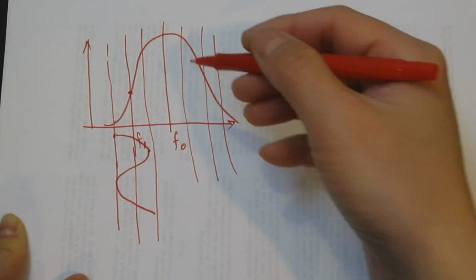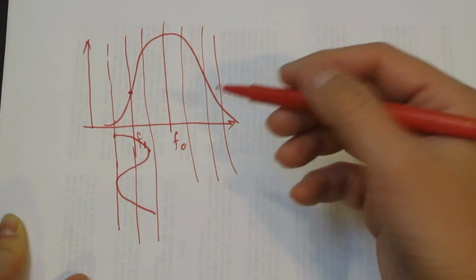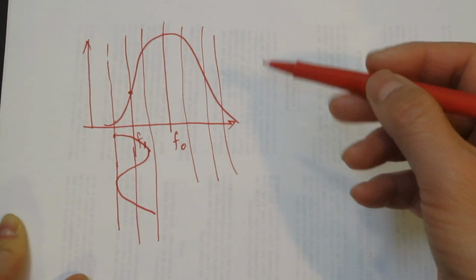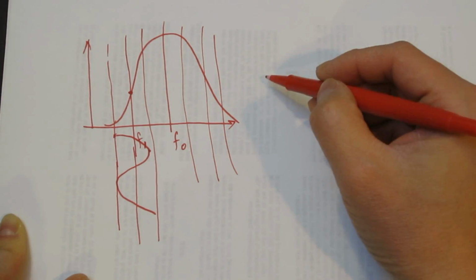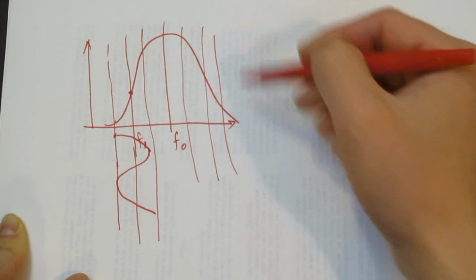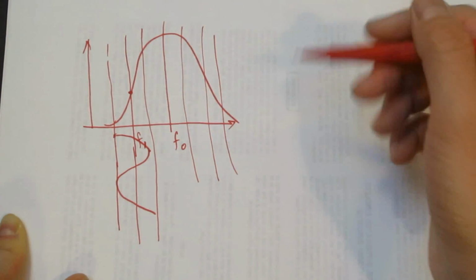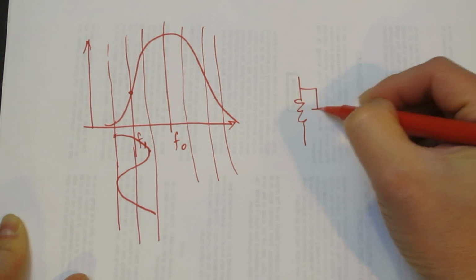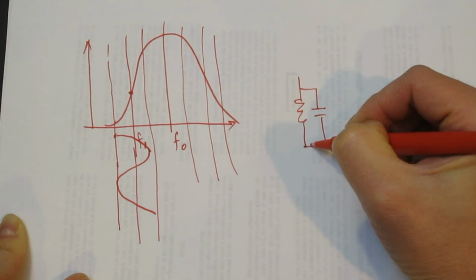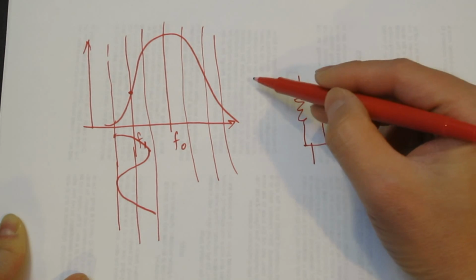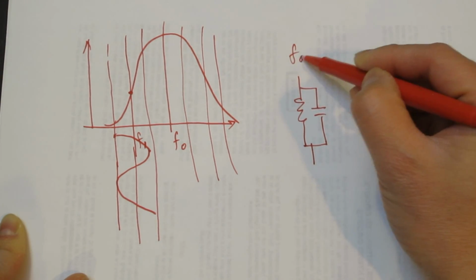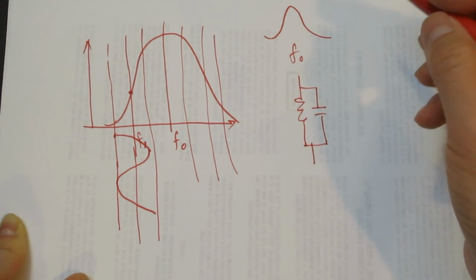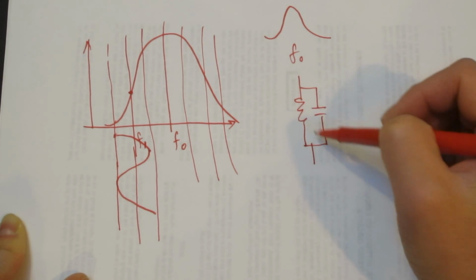The circuit for this type of detection is actually quite simple. You can basically build this in front of your AM detector and make it an FM detector. For instance, the simplest way to generate this kind of Gaussian-shaped bell curve is to use an LC filter. So we have a tunable LC filter. That's our frequency to amplitude converter, because this thing has a resonant frequency of f0, so it rolls off depending on the Q factor and a bunch of other characteristics of your LC.